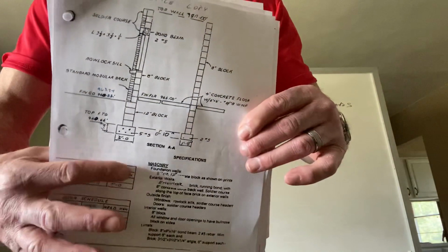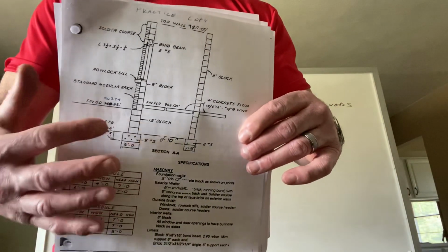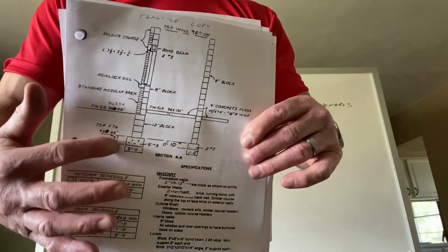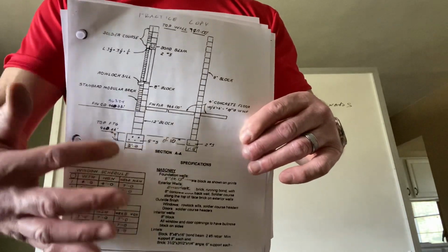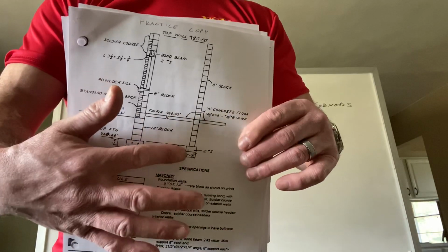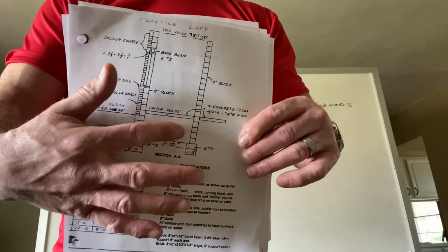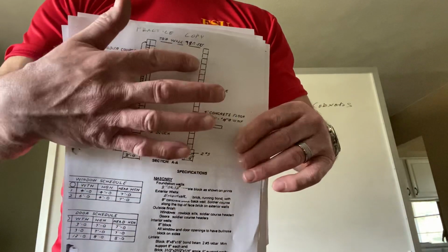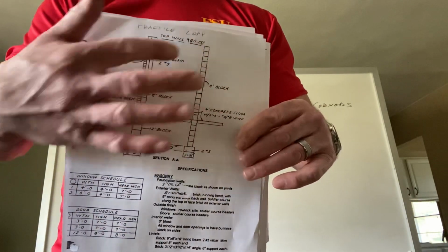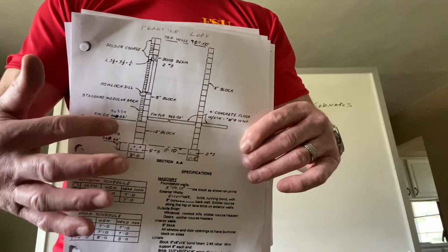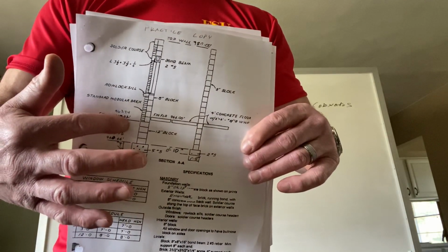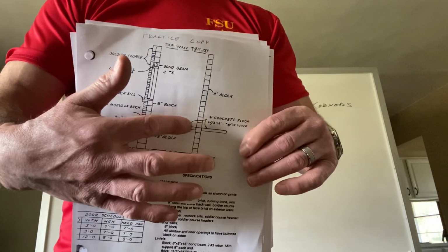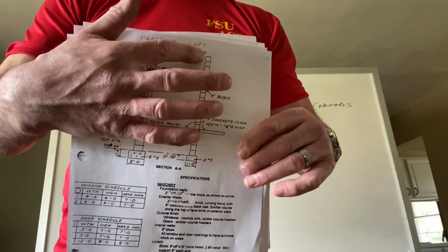Again, remember that we've been setting up this math problem the whole way through. We said that our exterior foundation took us from here to here, so we did the same thing on the interior foundation. We said we're going to go to the top of the same block, knowing that I was going to have to determine this block eventually. I need to know the height of that wall from foundation up. So we made the decision that we're going to call the top of the foundation right there, so I can determine this height.